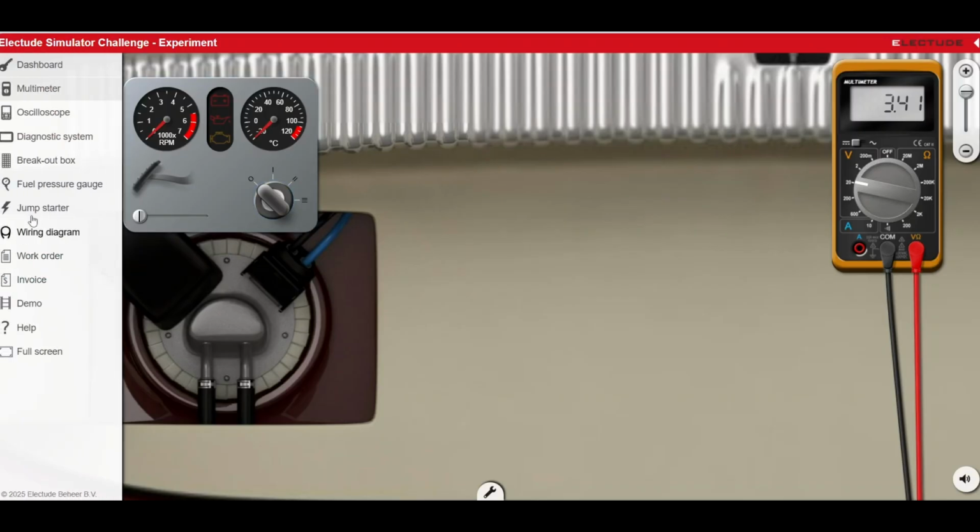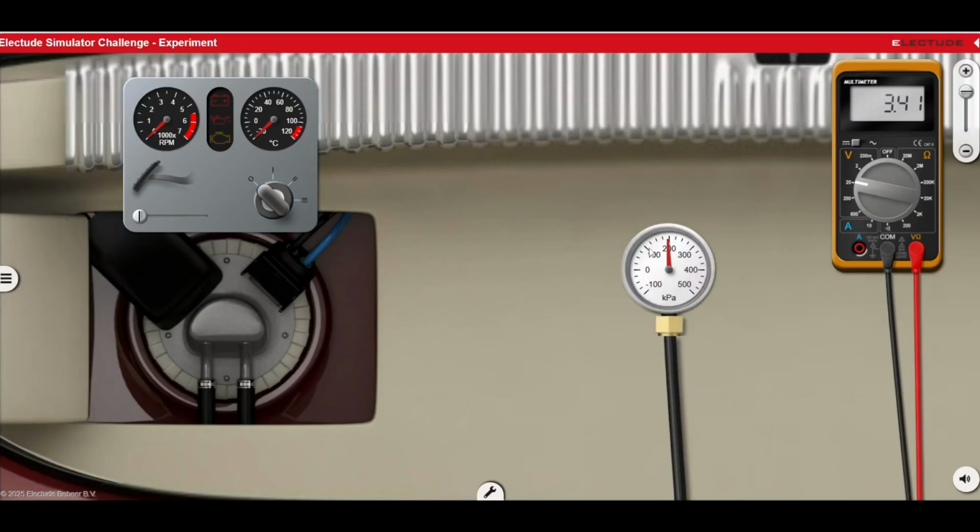Yeah, so let me bring the fuel pressure gauge out. You can see it is at 200 kPa, but it is falling a little. The longer the vehicle stays parked, the more this pressure falls, because the pressure that was built up in the pump or the fueling system of the vehicle leaks back, drip by drip, back into the tank.